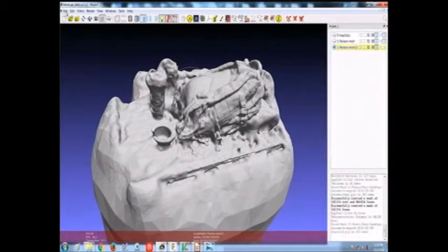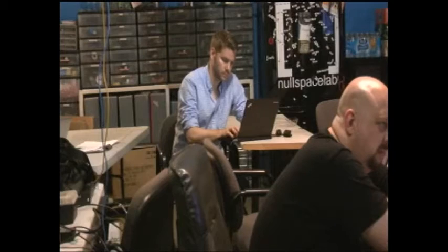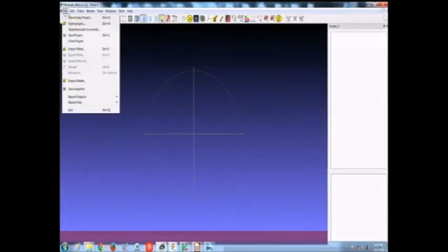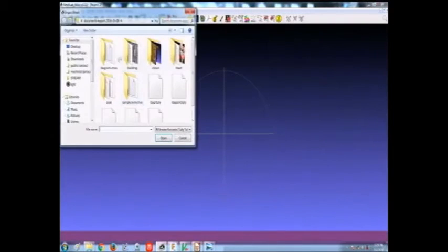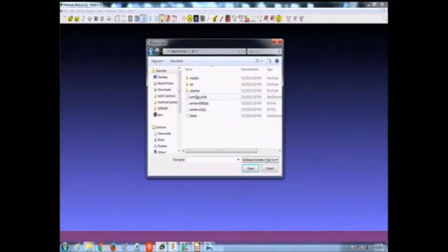So what we have to do is open a new project. There was a hidden data file that VisualSFM output with the sparse point cloud. Remember the point cloud where it only had a few hundred points, but it also had all of the aligned images on that surface. And MeshLab can work directly with all of those aligned images to project the color onto the resulting surface. So very close to where we saved that last file is cameras.vt2.txt, right? Is that it?